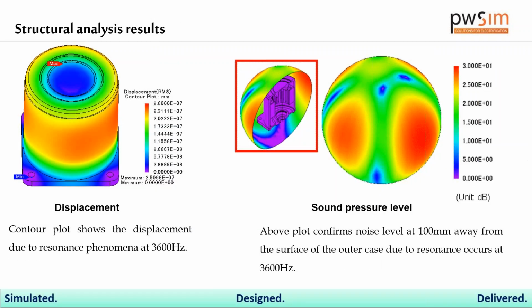So likewise, I told you, you begin with the design that you have, or you're getting some design, you begin with that, you input it into JMAG Express, you evaluate the model, you get certain torque, efficiency, etc. And once you fix the values, you can directly go to Designer, where you do the 2D FEA analysis based upon automatic meshing for the time being. And from there, you convert the model into a 3D model. And in the 3D model, you can do two types of analysis. You can do the thermal analysis, you can do the structural analysis.